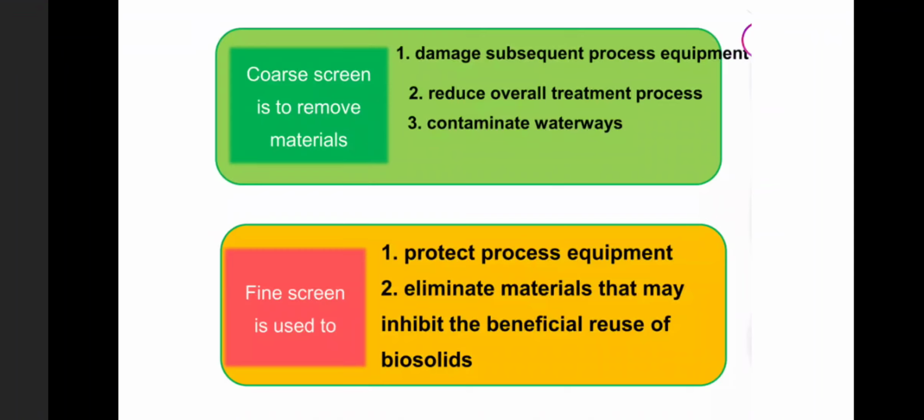Coming to the mechanically cleaned screened bars, we have discussed four types, but two types are much more important: the chain driven screen and the continuous belt screen. In the chain driven type, the water flow is in the horizontal direction at the bottom, and a chain is provided in the rig. With the help of an automatic drive motor, a continuous chain scraper is connected to the drive.